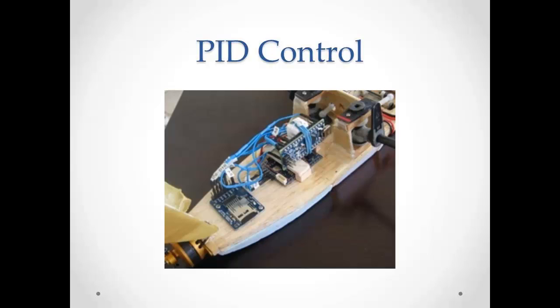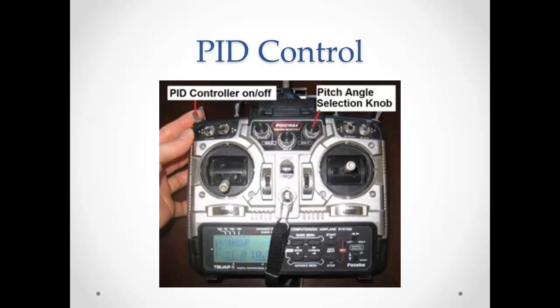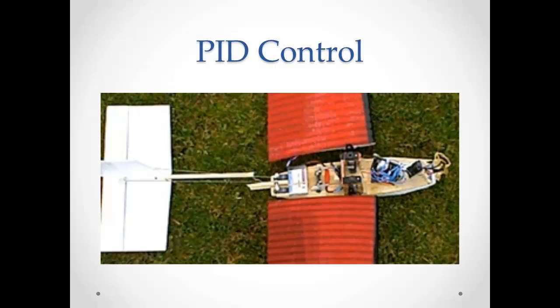After observing the pitch response due to manually controlling wing sweep position, the onboard microcontroller was used to close the loop. When the pilot was ready, he flipped a switch on the transmitter to signal the aircraft to take over pitch control, using only wing sweep for input. Unfortunately, a wind gust caught the aircraft on landing at the end of the flight test, causing it to crash. This brought an abrupt end to the flight test program.